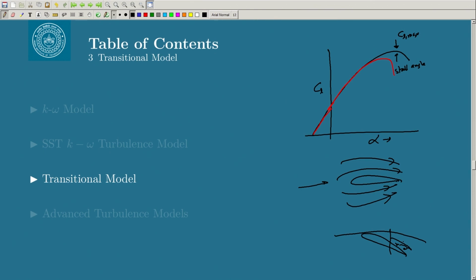As you go to a high angle of attack, you know that the flow is going to separate. So you should be very alert and careful, and change the model to find one which can make the predictions better. Even then it may not be very successful. Sometimes the flow becomes inherently unsteady, so there are some scales which are unsteady in nature.